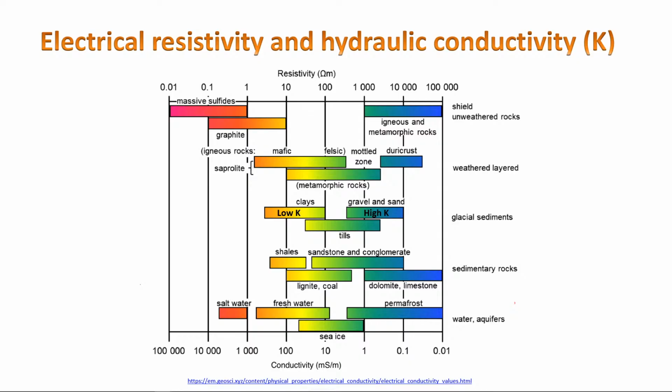Another application is to characterize the subsurface for remediation, to develop a groundwater model and design your remediation system, as I showed you in the very first video, where we needed to identify different hydraulic conductivity zones. To do this, you need one of these imaging methods. We will talk about this later when we come to modeling.